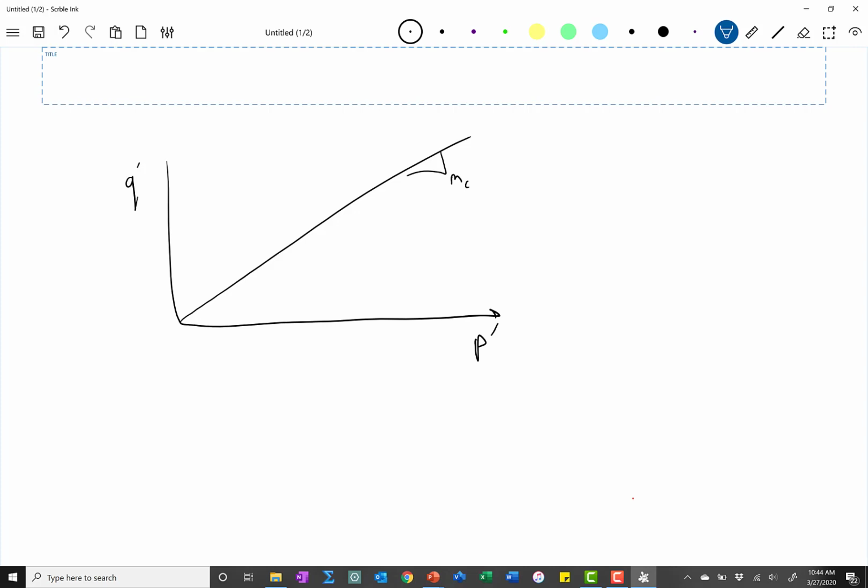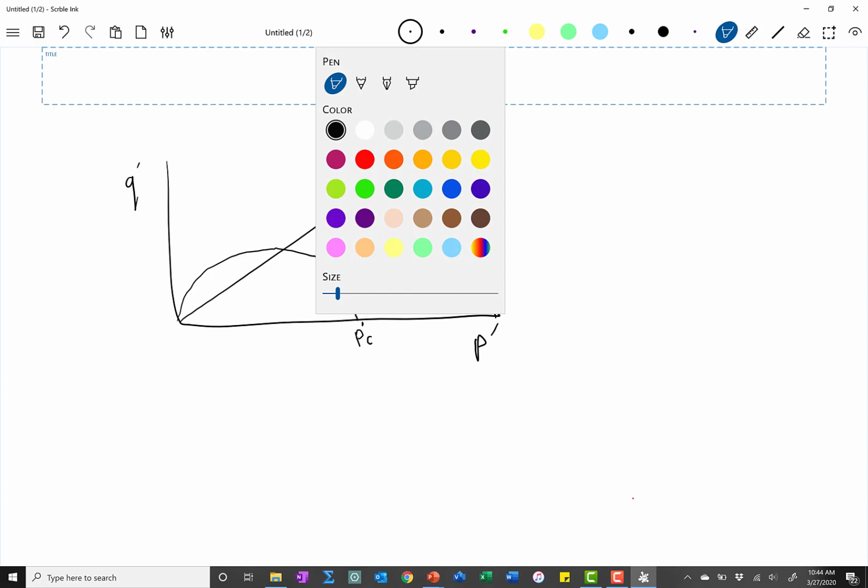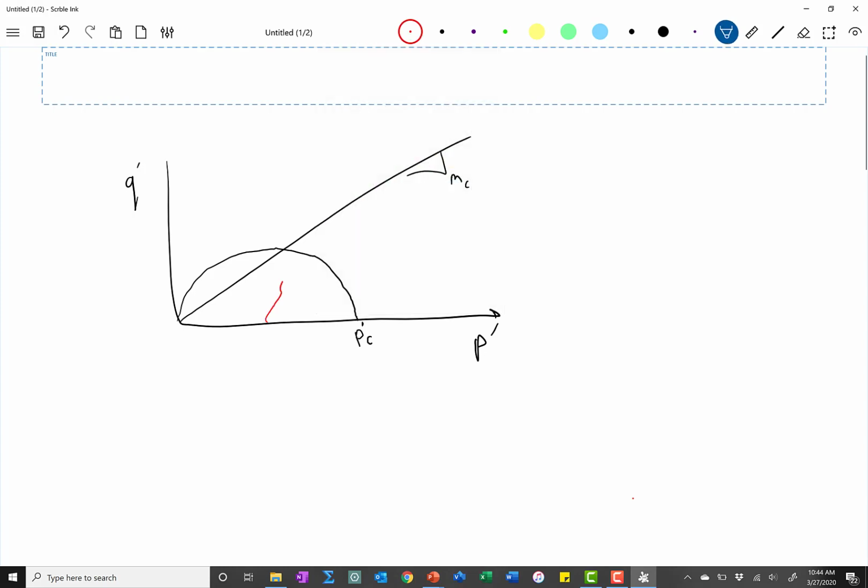Now, these failure surfaces are essentially circles, ellipses, bullets. They're different shapes. And they always correspond to whatever the pre-consolidation mean stress is of the soil. And as long as my stress path of the soil remains inside of this sphere, it doesn't matter which direction it's going, as long as that effective stress path remains inside of that sphere, the soil is going to behave elastically according to the rules of this critical state model.